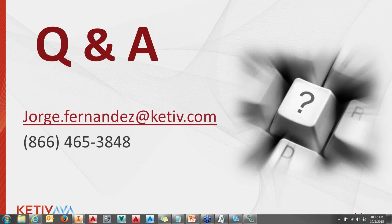Let me read another one here. Can you do an assembly FEA analysis where a part displaces or deflects to the point where it comes into contact with another part? Will it transfer the stress to the second part? The answer is yes, with dynamic simulation. You can set that up. Of course, it is all part of the setup and making sure you set up the contacts correctly as well as all the joints to be able to move or enforce motion for all the parts. So the answer to that one is yes.